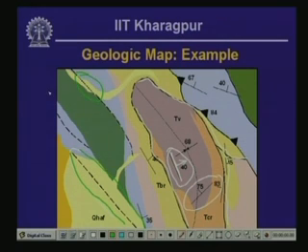These are dotted lines, actually thick dotted lines, they indicate faults about which there is no firm information, but these are actually inferred from the orientation of this fault at locations nearby to this area. Now, this feature here to the right of this geologic map shows essentially a thrust fault that is dipping at 84 degree angle.